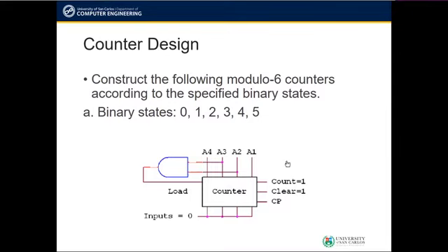In this case, for example, to check a count of 6, you may include A4 and A1 and connect them both to inverters or NOT gates and include them as inputs to the AND gate here. In this way, you can be sure that you are exactly checking for the binary value 0, 1, 1, 0.